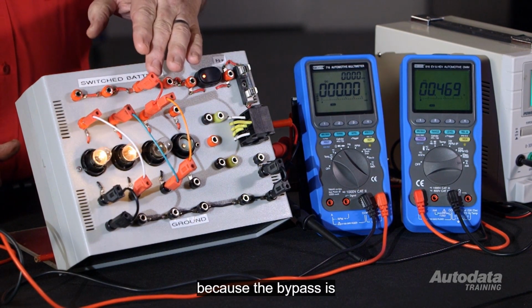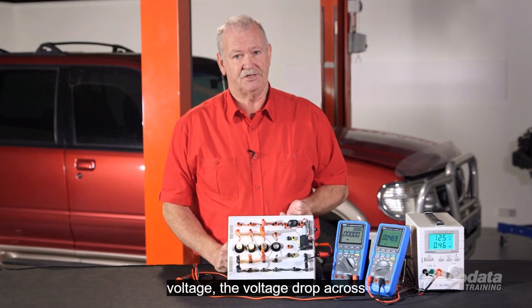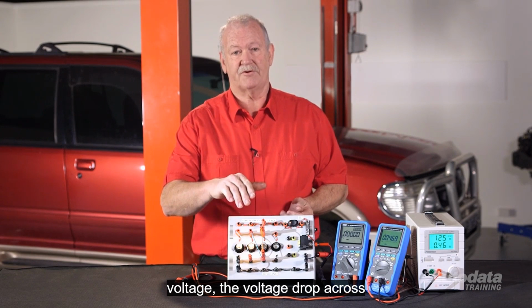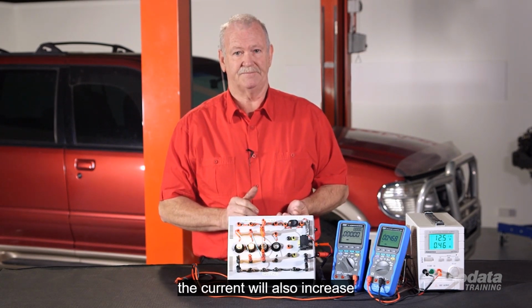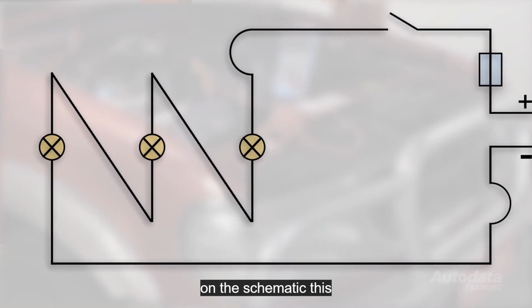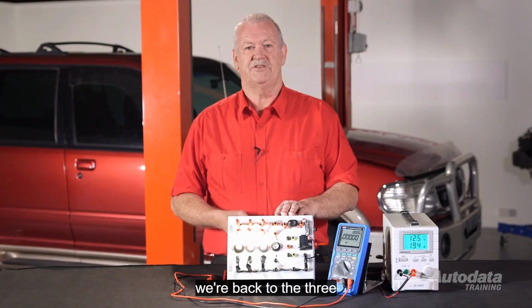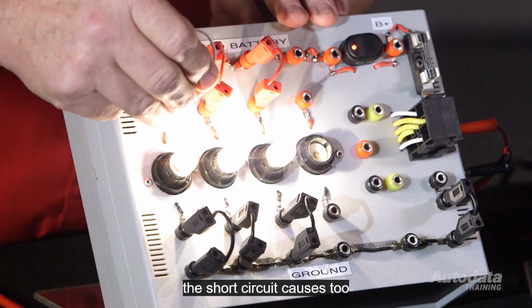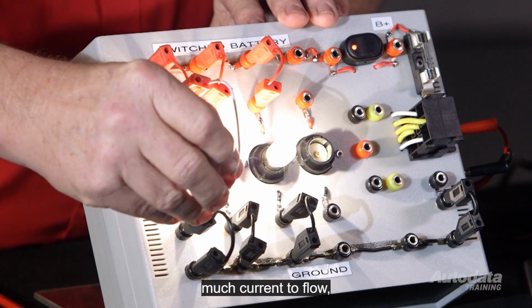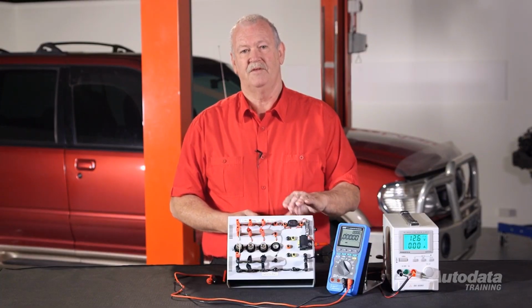Because the bypass is now going to the positive side of the circuit, this would be a short to voltage. The voltage drop across the globes will increase, and the current will also increase. On the schematic, this is what the short to voltage would look like. We're back to the 3-globe parallel circuit. If the short circuit causes too much current to flow, the protective device will operate.